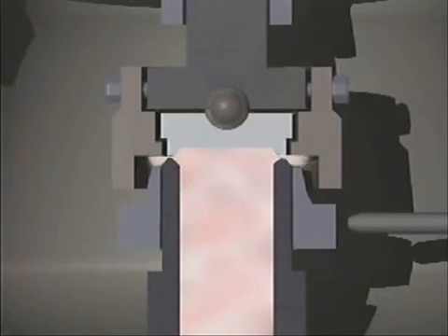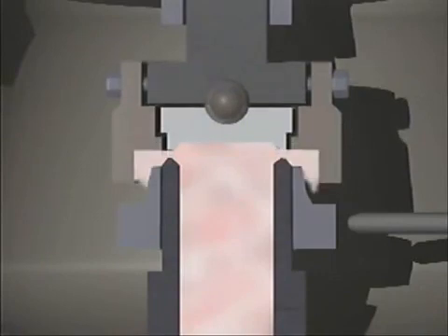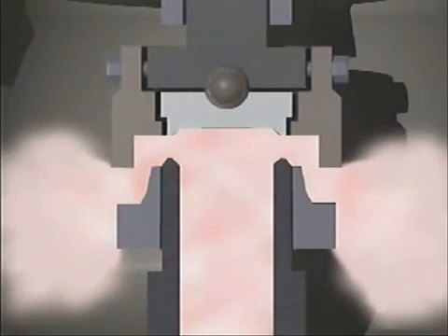The pressure of fluid directed against the disc lifts the disc off the seat. While the valve briefly simmers, the flow of the fluid as it discharges outside the valve's seating area increases the lifting force. Then the reaction hood deflects the discharging fluid downward. Creating a reactive force by deflecting the flow of the fluid further increases the lifting force and causes the valve to pop open. As system pressure returns to normal, the valve closes.